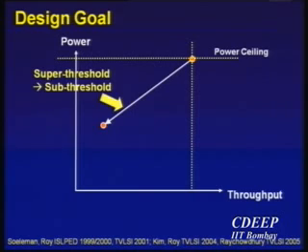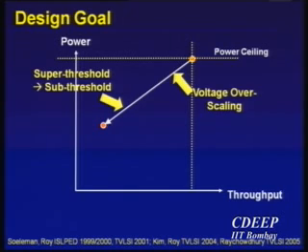So what I can do now is scale my supply voltage, and what does scaling of supply voltage do? That reduces my power consumption or energy consumption, but of course I'm going to lose performance out of the device. If I'm really aggressive in scaling my supply voltage down, I can go down to about 200, 250 millivolts, and then I'm going to go into the subthreshold region. Again, you can do some very interesting things. The thing that I'm going to be focusing on is voltage scaling, and I'm going to go back to that in just a minute.